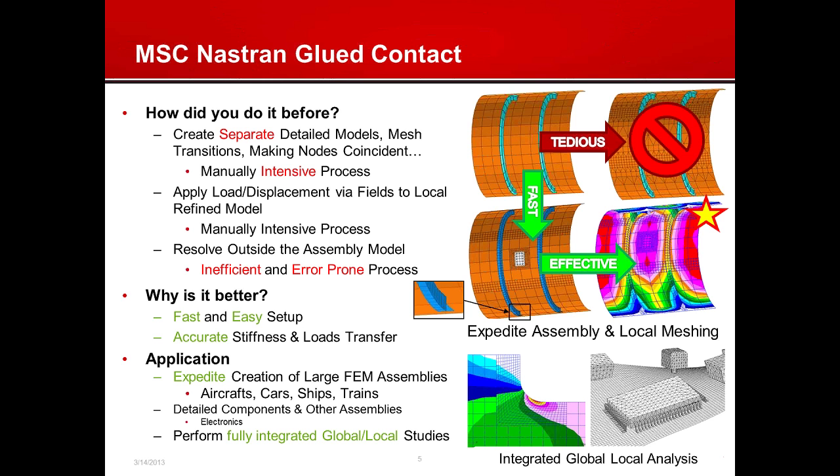That sometimes is impractical, and instead of having large transitions of triangular elements which will skew your stiffness, you can decide to just remesh locally to some extent an area and glue it to the coarse mesh adjoining it. Now, obviously, you have to use your engineering judgment when doing so, so you have to make sure that you satisfy the rules of FEA analysis, where if you have a large mesh ratio between a boundary from a large coarse mesh to a fine mesh, if that mesh density ratio gets too high, obviously the stress and strains might not be that nice in that area.